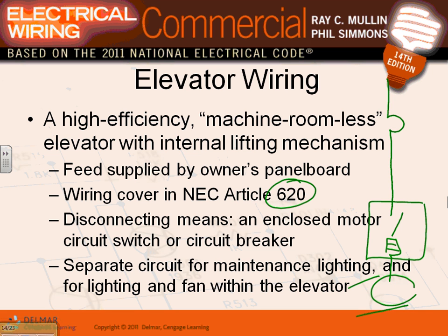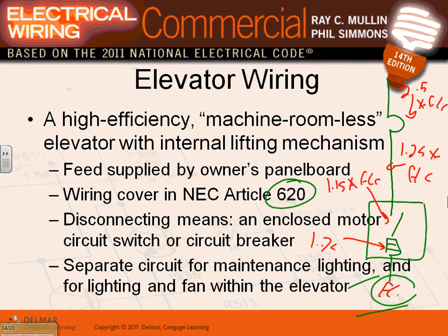How do you size it? This is the elevator. You're going to size this one, guys, 2.5 times full load current. Conductor, 1.25 times full load current. Disconnect. How do you size the disconnect? 1.15 times full load current. Fuse overload here, 1.75 times full load current. And there's a big thing here that we're not showing for the elevator, which is the controller.